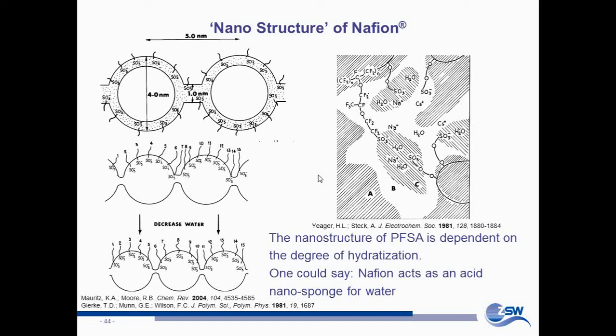So in the very dry state, the hygroscopic sulfuric acid-like behavior dominates. Then there is a degree of hydration which is in equilibrium with the environment, where you have an average conductivity somehow. And now if you want to go to the very high conductivity, then you will realize that the material loses water faster than if you put a drop of water next to the material on your tabletop.